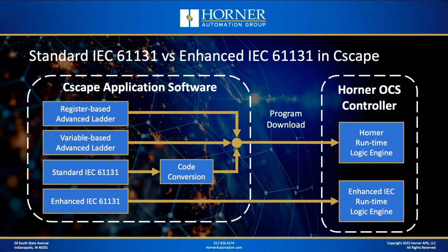Standard IEC, you can see there, once it is created by the application engineer, Cscape then has to do a code conversion before downloading it to the OCS. And on the OCS, that download is made to the traditional Horner runtime logic engine, just like register-based and variable-based advanced ladder. However, IEC 61131 Enhanced has its own runtime logic engine that's existing on the Horner OCS.